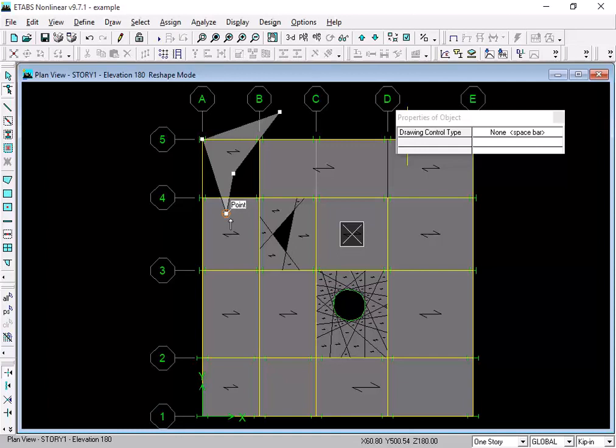Now for example, you say, okay, these are only 4 pickup points, how can we make it more close to circular shape or something not trapezoidal, something in between circular and rectangular. To make it more close to circle, you need more pickup points. Okay, with 4 pickup points you can't make it close to circular or some different shape.